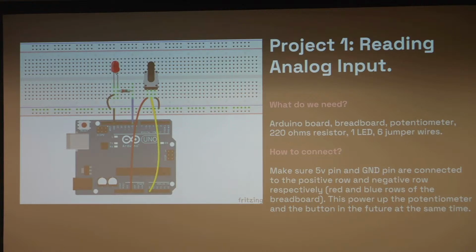We're supposed to thread the ohm resistor underneath it. Yes, you might move it in a U shape, and make sure it touches the bottom. I don't think the potentiometer needs the resistor. That's only for the LED.